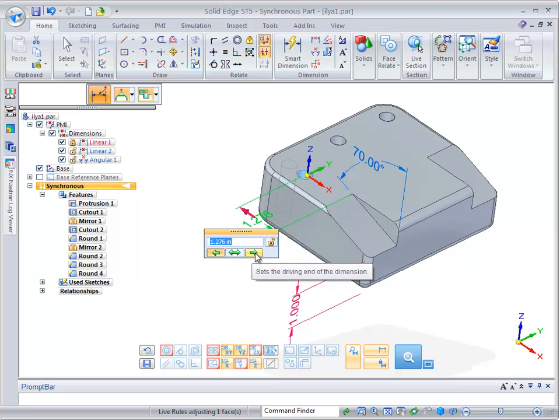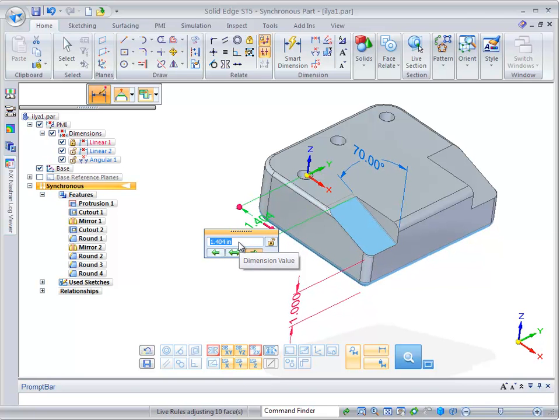And changing the direction arrow makes the angled face move along with the bottom of the part, since the 1-inch dimension is locked. So that's some pretty nice flexibility in my book. These are things you could never coax SolidWorks to do. Being able to change the design intent on the fly in this way can save you a lot of time if you ever have to make an edit that you didn't expect to make.